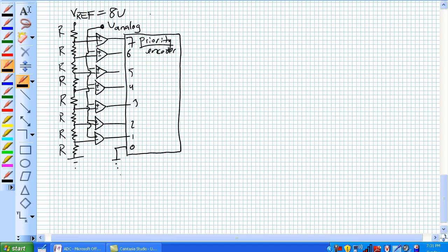Let's say we have our analog value. This guy is enabled at a frequency twice as fast as the naturally occurring frequency of whatever that analog signal was. And let's say it's sampled and it happens to be 3.5 volts and it's held at 3.5 volts. And now we are going to start quantizing it. So 3.5 volts.